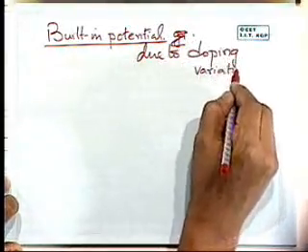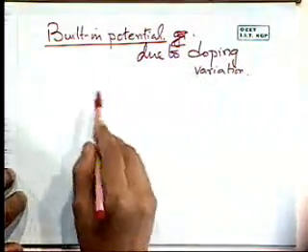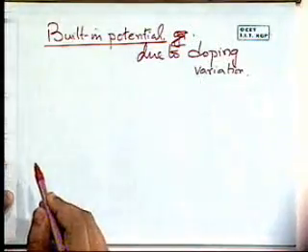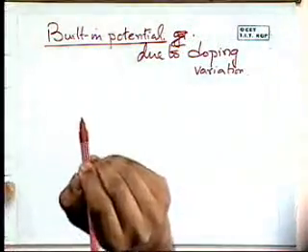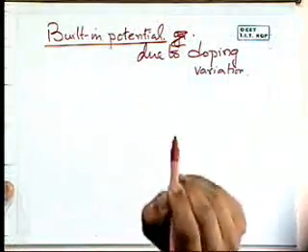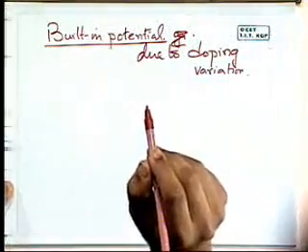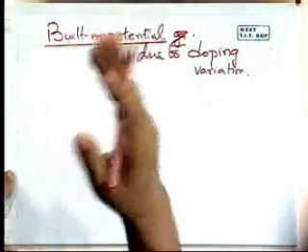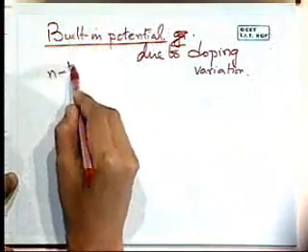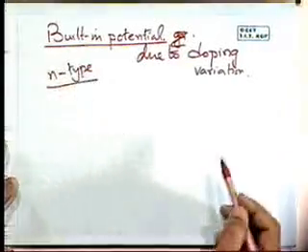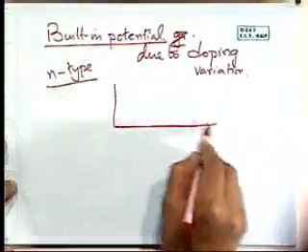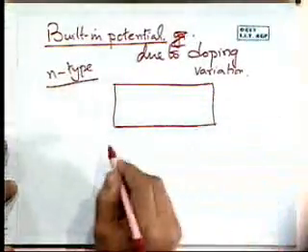So here we have a sample that, as I said, we may have doped by diffusing in something from one end. And we are going to consider what happens to this sample immediately after we stop that diffusional process. So there's no more creation of those extra donors or acceptors, as the case may be. We will take the case of an N-type sample, and we say that there is a concentration gradient along X from one end to the other end.